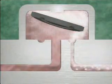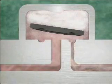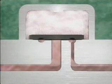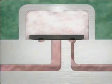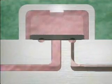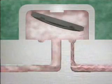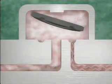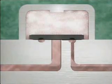When sufficient pressure builds up here while pressure on the underside of the disc has been reduced, the disc is forced down onto the seating surfaces, which closes the trap. The disc is held closed by the pressure of the steam that's in the chamber above the disc. When this steam condenses, changing to a liquid state, and the pressure above the disc becomes low enough, the disc rises and condensate flows out, until velocity and pressure conditions within the trap again cause the disc to snap down on the seating surfaces, closing the trap.